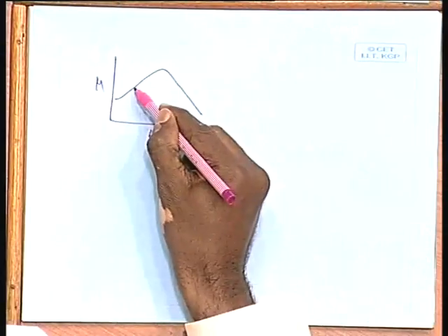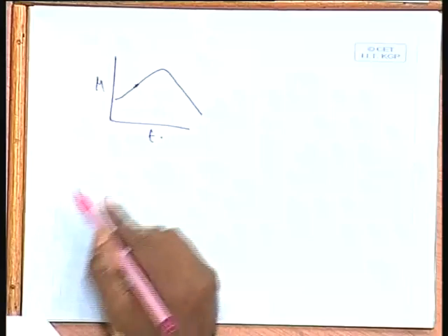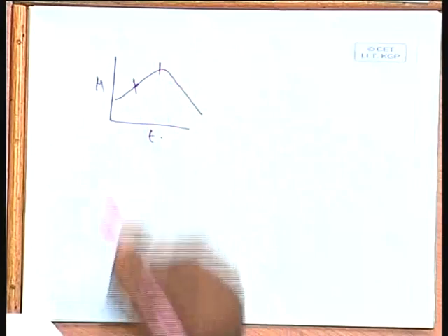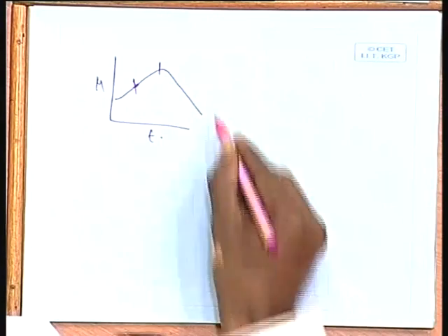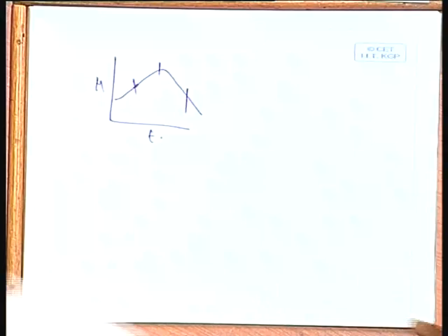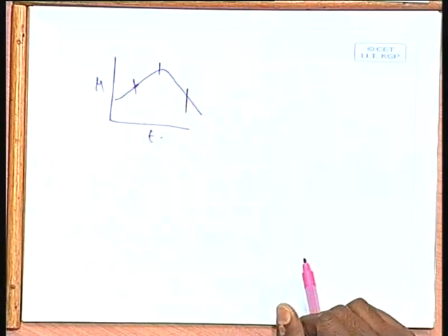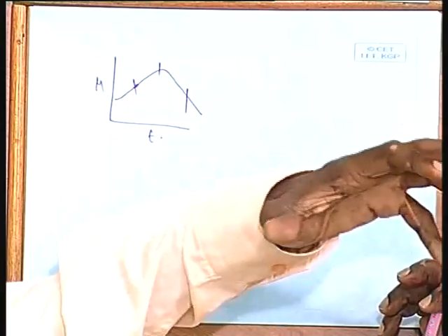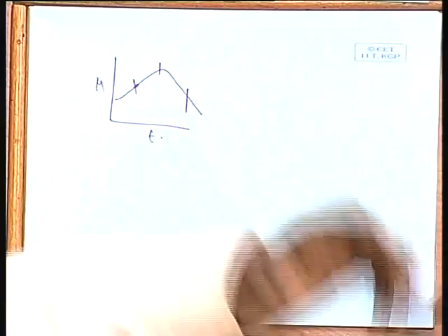And we say this is because you have coherent precipitates coming at this stage, and then coherent and semi coherent here, and then once the precipitates grow and become bigger, they become incoherent because of the too much strain that is required to maintain coherency. That strain is so much that the precipitate would prefer to be incoherent rather than maintaining the coherency, and once it becomes incoherent, then you lose the strength.